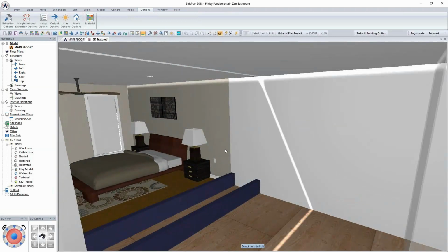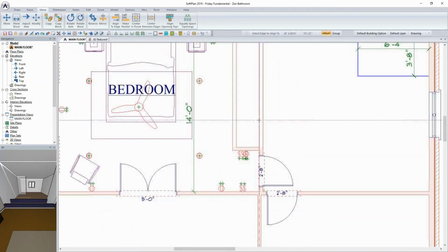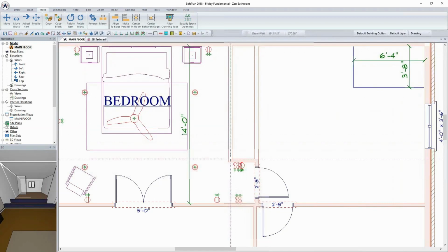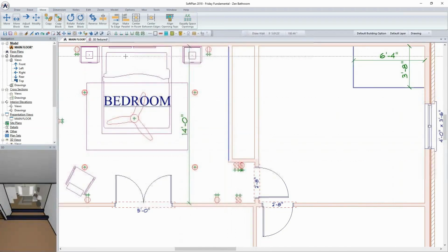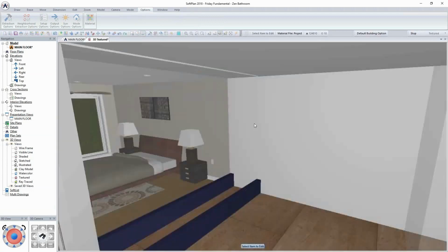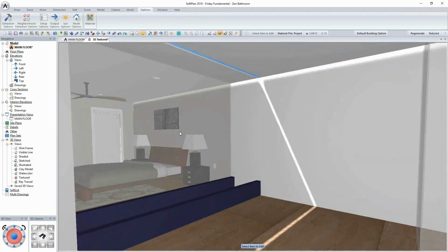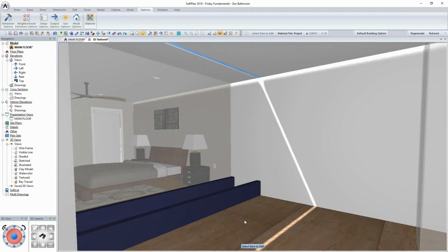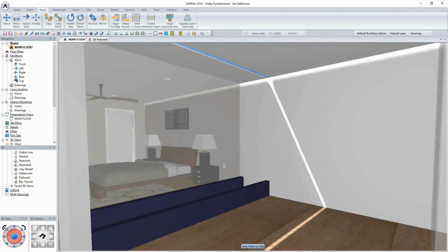And this is where we're going to place the bamboo, and then we'll place a glass wall sitting on top. Okay, so just kind of building this up, getting my walls in place first. Now, I can use the same draw select, and I could pick this glass wall. I could draw that in running down the middle, or over here on the edge, something like so. As I do that, I'm going to have the glass placed, and you can see it here inside the 3D, right? At this stage now, you could modify the height and change the offset. But the key is that that's been placed in there.